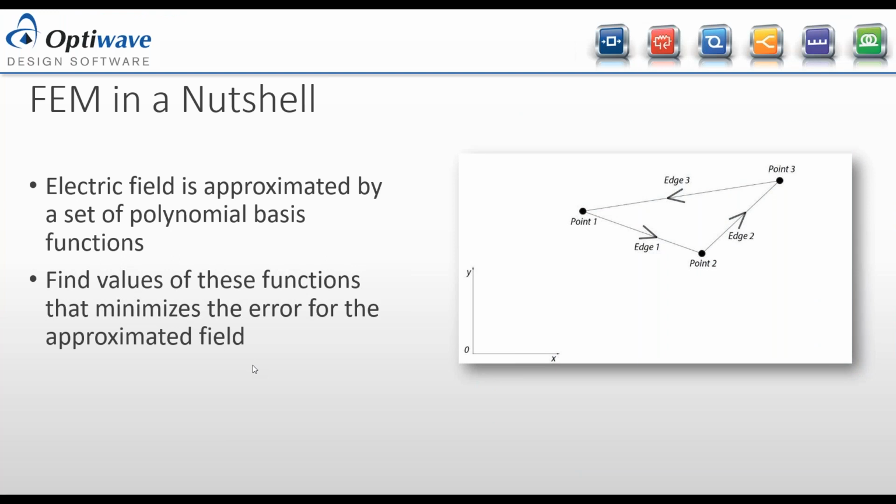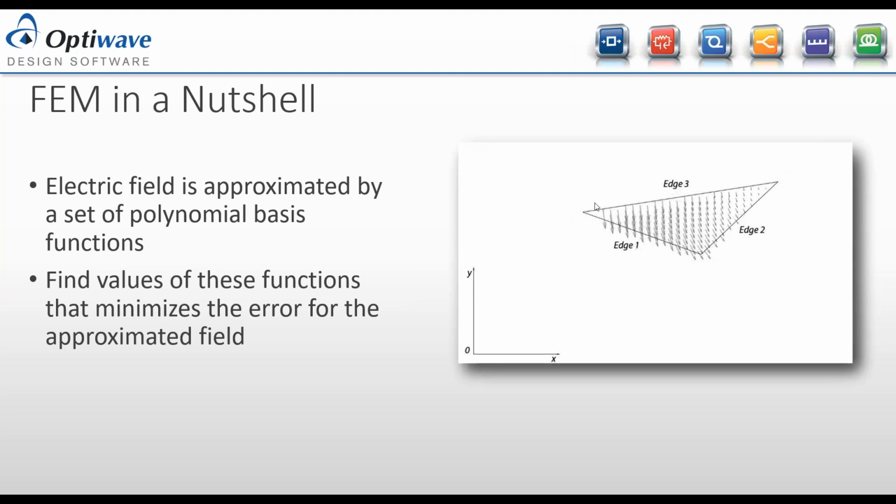So the next thing I want to explain is how do you approximate a field with the finite element mesh, and what that means. I mean, how does that mean you should get a better approximation? What choices should you make to get a better result? So, as we said, we approximate the domain as this mesh of triangles, and then over each of these triangles, here we have an example of one that's isolated. We use these polynomial basis functions.